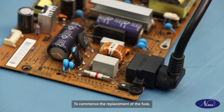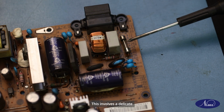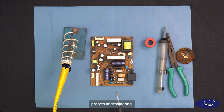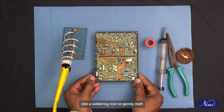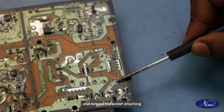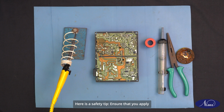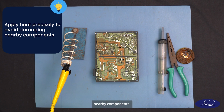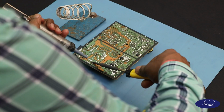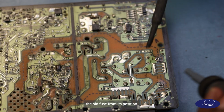To commence the replacement of the fuse, first we need to carefully remove it from the board. This involves a delicate process of desoldering. Use a soldering iron to gently melt and remove the solder attaching the fuse to the circuit board. Here is a safety tip. Ensure that you apply heat precisely to avoid damaging nearby components. Once the solder is removed, you can lift the old fuse from its position.